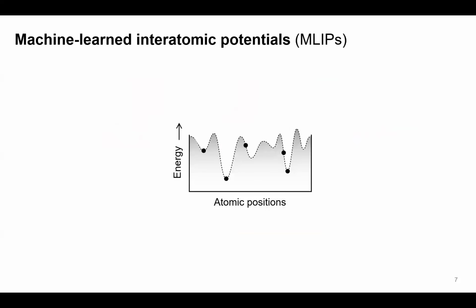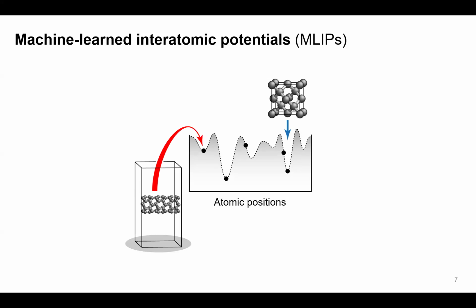But to go one step back and say, what exactly are these tools and why do we need them, right? So the central task probably when you're running atomistic simulations is understanding what is sketched here as a cartoon, which is the potential energy surface, right? So you need to know the energy of a system as a function of where the atoms are. So if you're looking at elemental carbon, you would have maybe the diamond structure in a local minimum up here. You would have a carbon nanotube, it's maybe in a simulation cell like this.